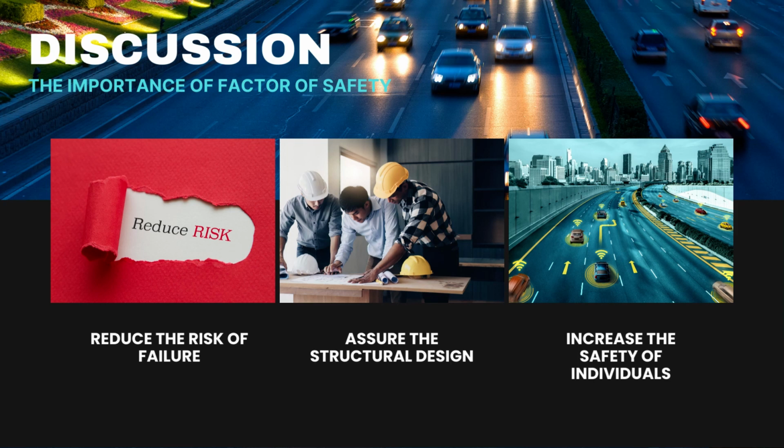The second one is about assuring the structural design. For the rotor disc, as we know, structural integrity is essential for the consistent and reliable performance of the braking system. By applying an FOS, we can ensure that it can withstand the stress and the heat generated during the braking process without experiencing deformation or failure.